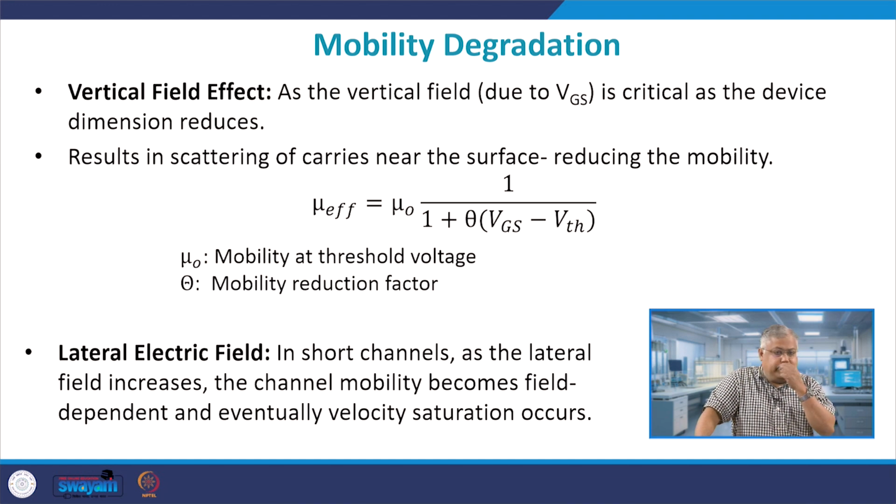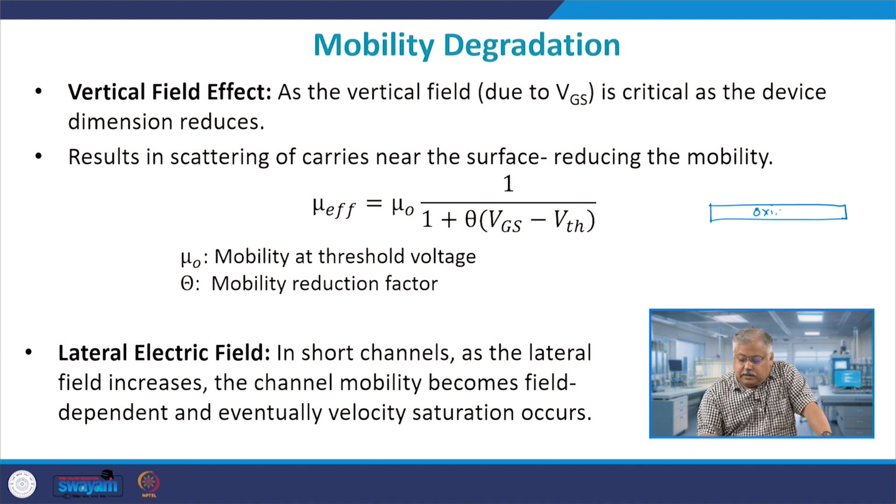I will try to explain to you first from the physics of the device and then from the mathematics. So, you see, in a simple silicon dioxide interface, this is my oxide and this is my metal, and this is my silicon here, and when you apply a positive bias here, then Ey, assuming Ey to be the electric field in this direction, goes on increasing, right.